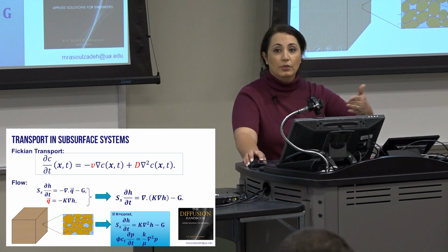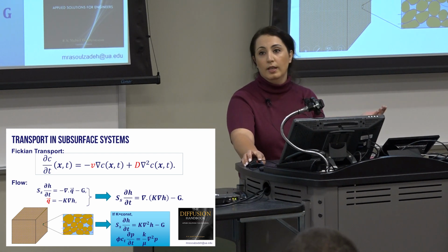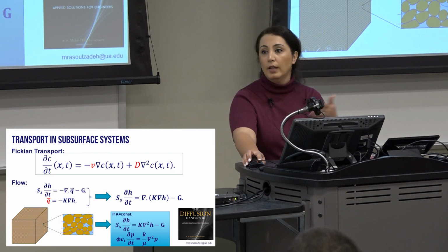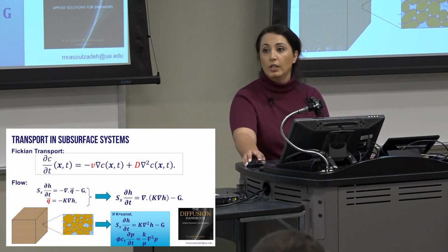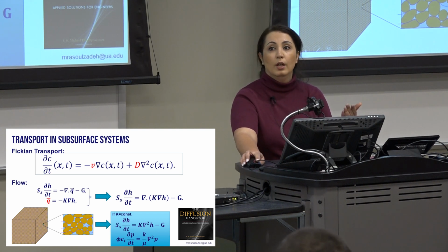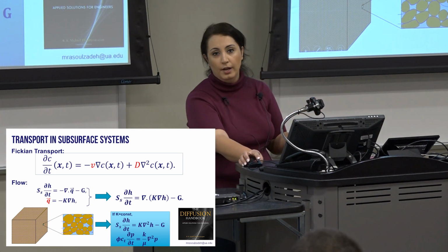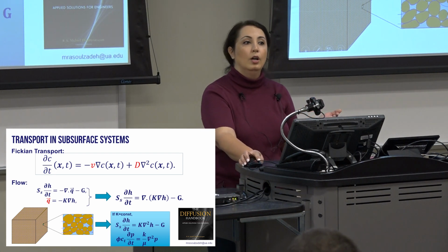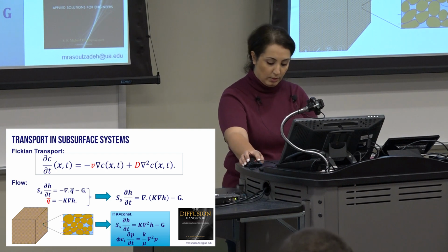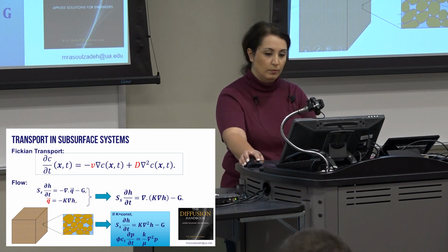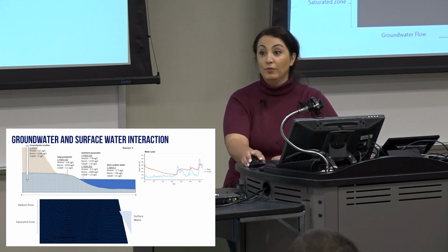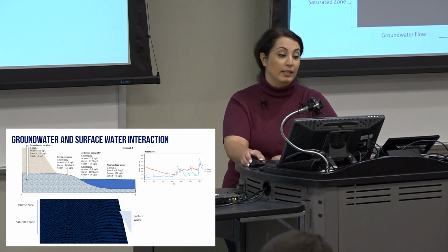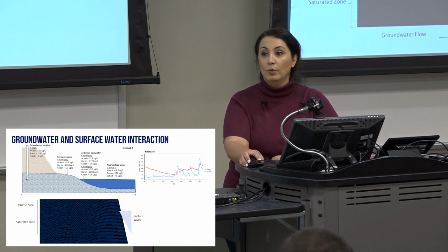It comes to transport modeling. So transport is the classic advection dispersion equation, as we know, and once we know the flow, we know the fluid velocity at each location, and we can solve for transport, again using either analytical solutions or numerical solutions.